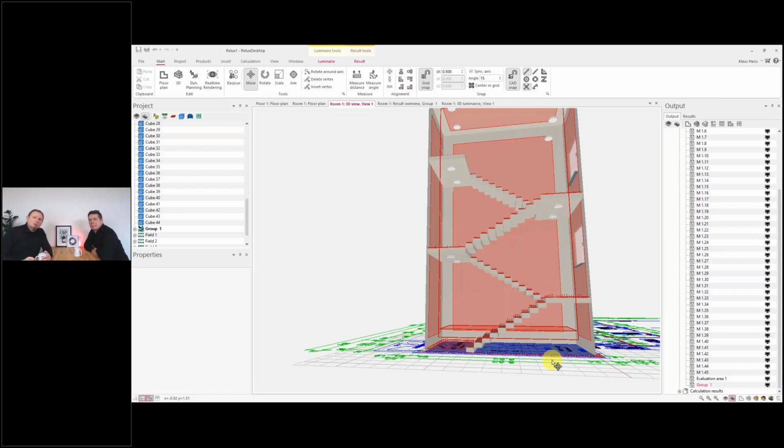But there's also an option to have, for example, a side view and plan view with the staircase, and then to create a polygonal extrusion volume in Relux. You just make the polygon of the base area and then extrude it to the width of the stairs. This is also a common method if you have the side and plan view.